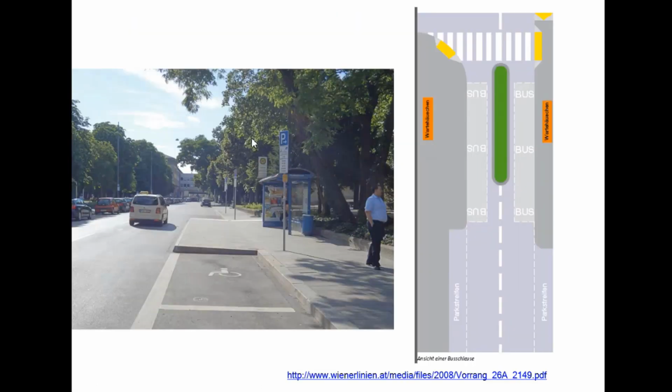As you can see here, when the vehicle stops at its specific location, which is a dedicated bus stop, the only issue is that the same bus, when it stops exactly in that place, needs a lot of distance to move on. So in that particular section, we can also introduce the same bus bulb concept.